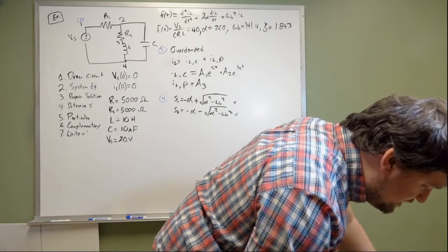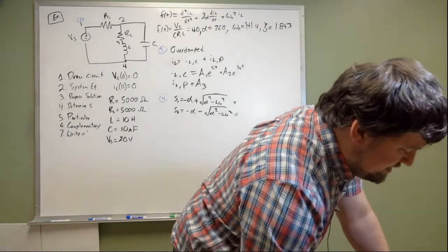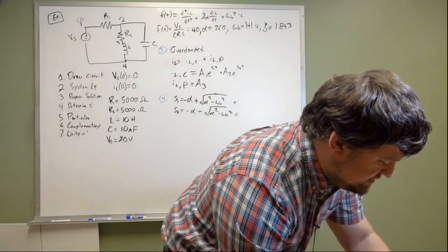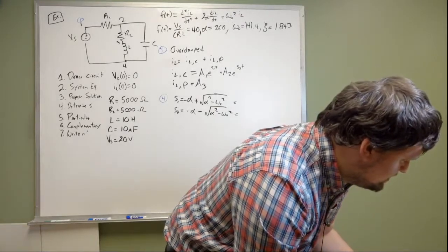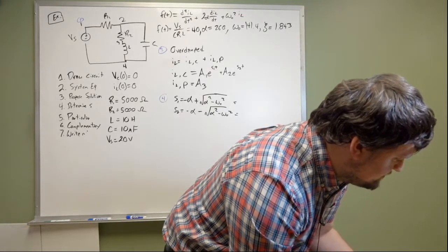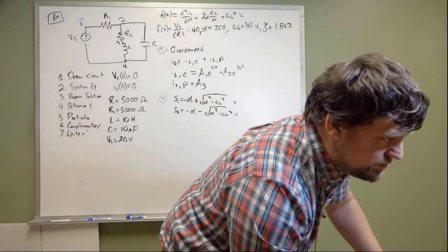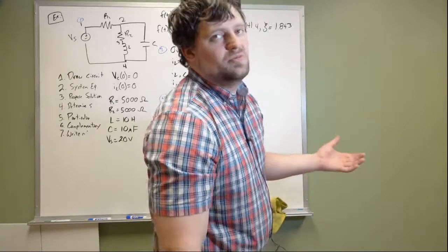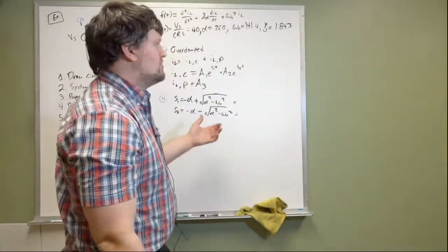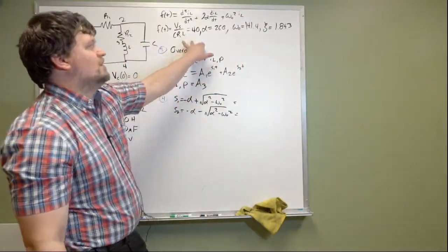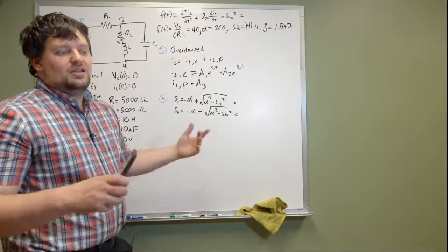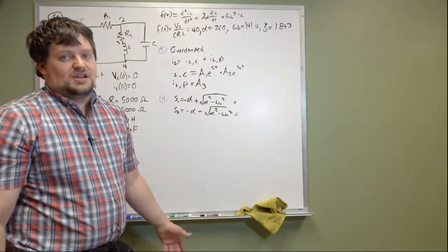It does only apply to the overdamped and the critically damped case, I believe. You'll notice that there is no S value in the underdamped situation, but it gives you the formula for the natural frequency. Again, it's just using formulas from the book. And these formulas are derived such that once you find the value of alpha and omega naught, the solution process is identical.